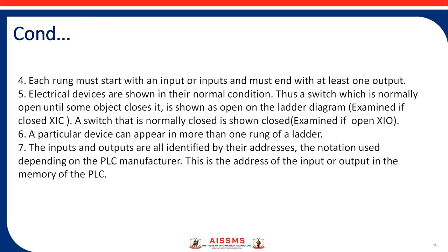Electrical devices are shown in their normal condition. Thus, a switch which is normally open until some object closes it is shown as open on the ladder diagram. It is also known as examined if closed, that is XIC. A switch that is normally closed is shown closed, that is examined if open, XIO. Next rule is a particular device can appear in more than one rung of a ladder. The inputs and the outputs are all identified by their addresses, the notation used depending on the PLC manufacturer. This is the address of the input or output in the memory of the PLC.